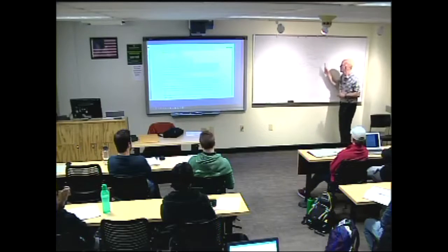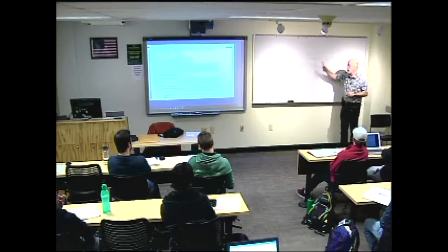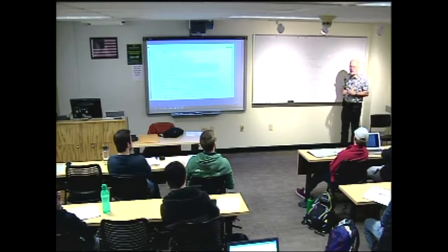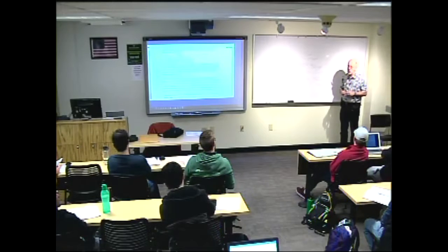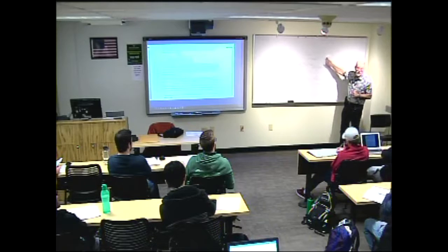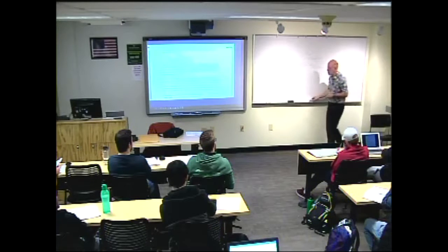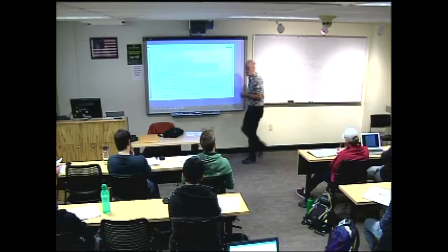So what do I do to get from here to here? Do I multiply by R, divide by R, multiply by R squared? R squared. Not just R, but it's R squared in order to change from current squared to voltage squared. So make sure that you're using the square of the resistance in that case.